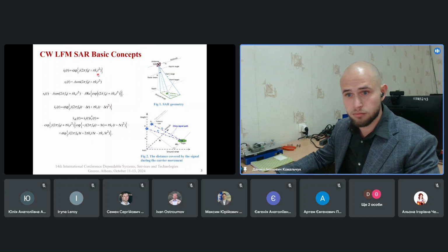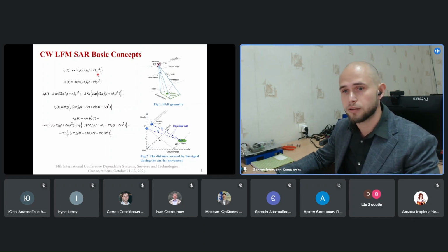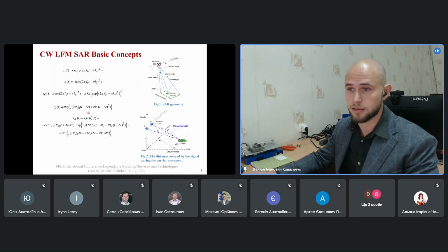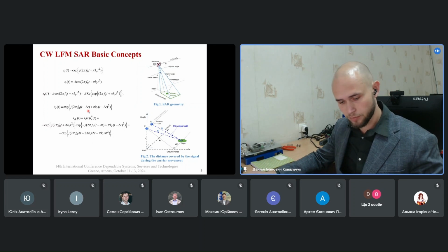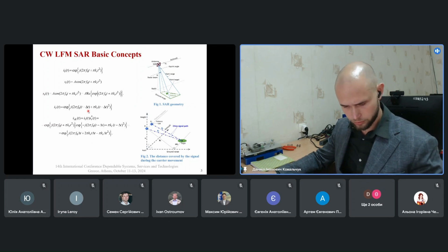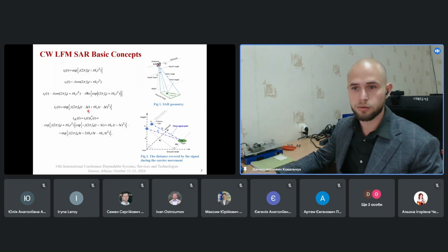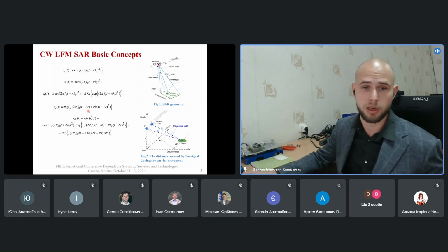First is the sensing signal with linear frequency modulation, transmitted form. The received signal is similar to the transmitted one. The only difference is that it is time delayed by delta t, the time it takes to reach the target and get back. The final step involves multiplication of the two signals, which is needed to extract the phase difference between the two signals and get the information value.